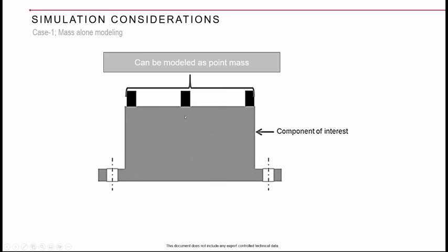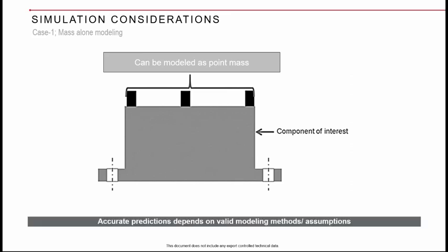to the mode shape of my manifold. The way the manifold vibrates in the vertical direction here, or in the lateral direction here, this is going to be only an added mass, and it's not going to change the behavior because of their stiffness. So I can definitely simplify them as point masses, so that I can take advantage of the reduced number of degrees of freedom or number of equations to solve in my FE analysis.